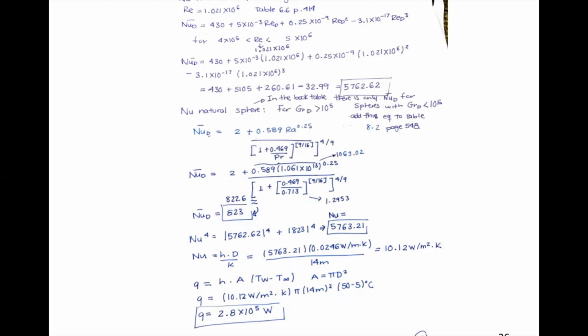Okay, so this was an example already prepared for you to add both, but in some problems you need to decide if you really need to add the contribution of natural convection. And how do you decide that? Well, either with the ratio of the Reynolds-Grashof, or you go to your graph in your textbook and determine in which area of the graph you are, and if mixed convection is important or you need to evaluate as mixed convection or not.